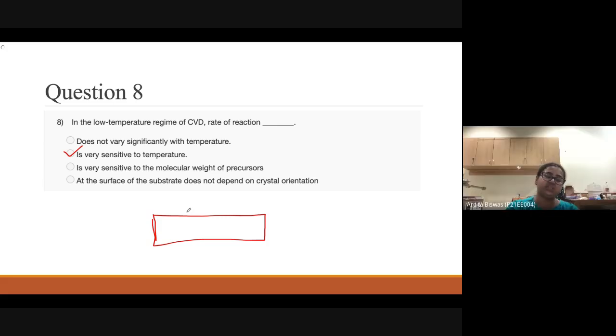See, this is a structure where we can grow using atmospheric pressure CVD. This is a three zone system: the first zone, the second zone, and the third zone. Here is the inlet pipe, where the argon gas goes in, and this is the outlet. The exhaust gas, after the deposition, can go out through here. And here we use some precursors.